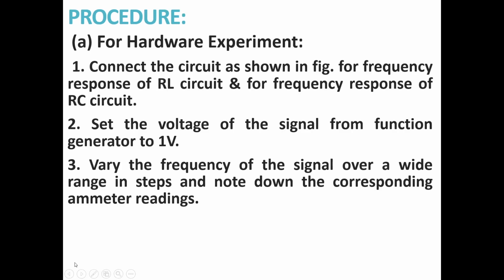Next, procedure. For the hardware experiment, connect the circuit as shown in the figure for frequency response of RL circuit and for frequency response of RC circuit. Set the voltage of the signal from function generator to 1 volt. Vary the frequency of the signal over a wide range in steps and note down the corresponding ammeter readings.